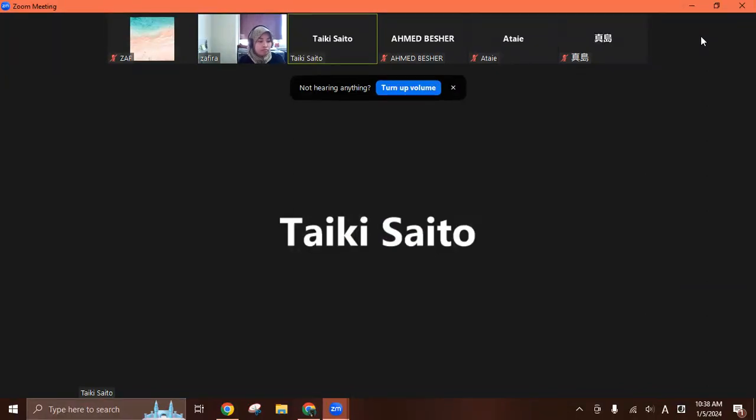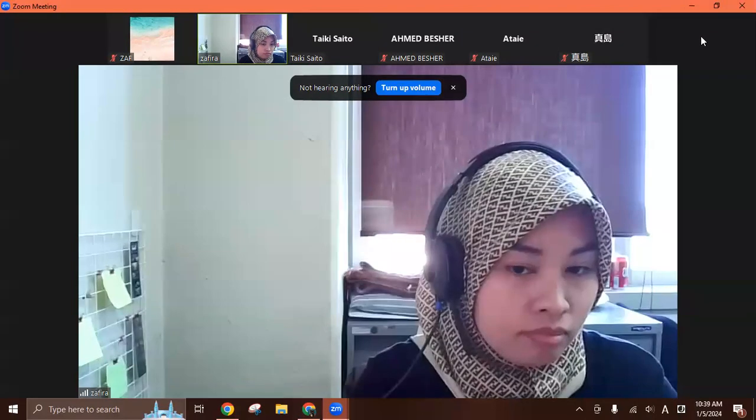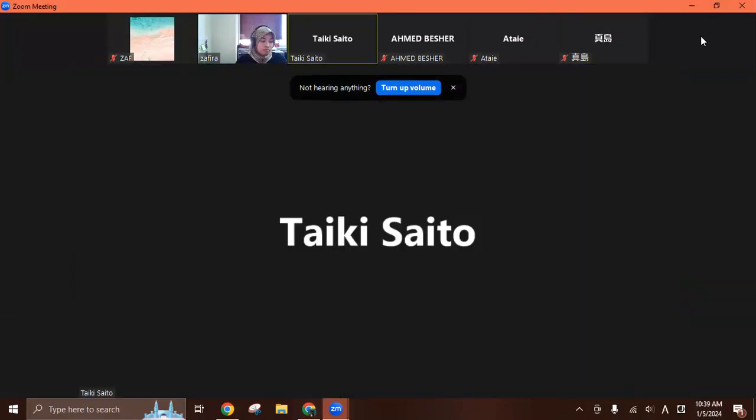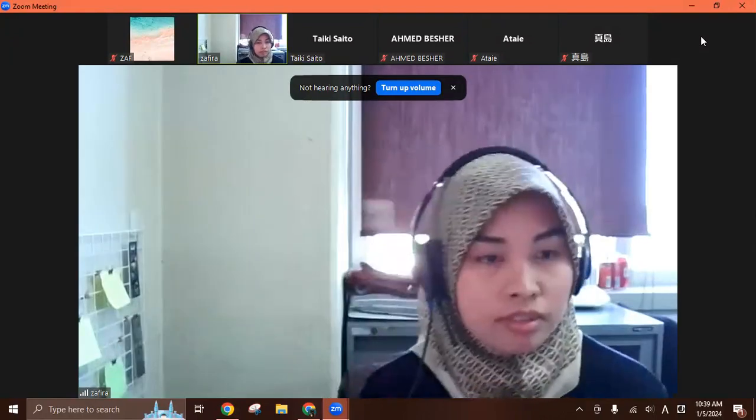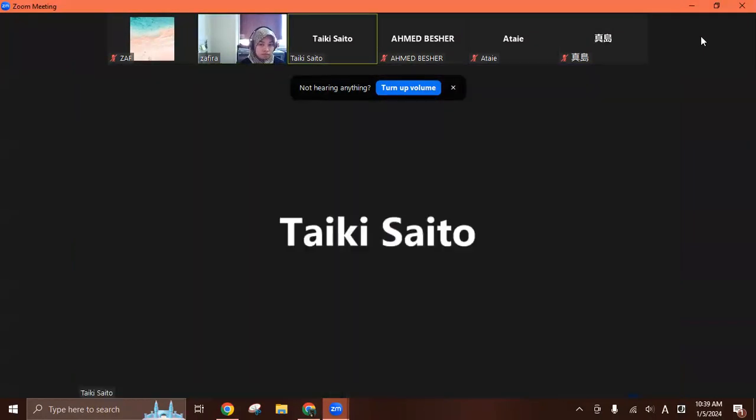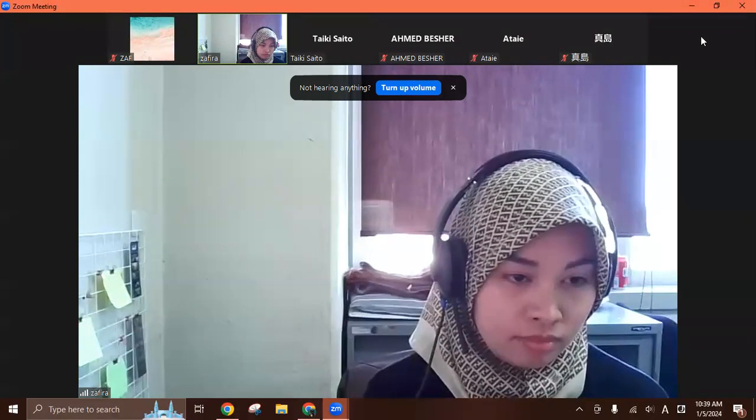Well, actually, they worry about the friction damper. I mean, if you put the friction damper in the middle of the coupling beam, you know, a viscoelastic damper can deform in any direction, right? Yes. Tension, compression, shear, any direction. But a friction damper can only deform in one direction. There is a long hole with a bolt, and the bolt is sliding.